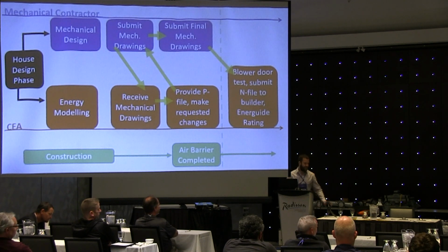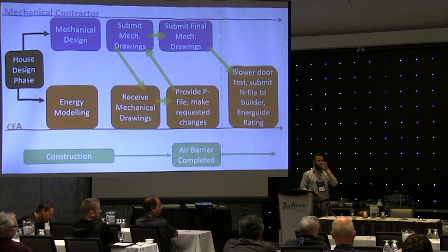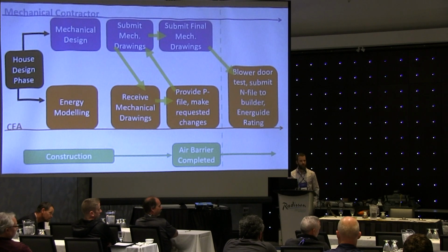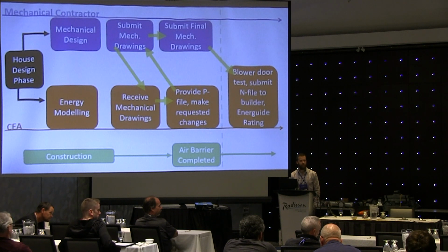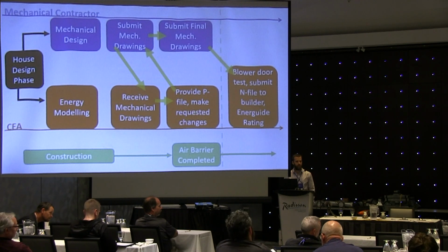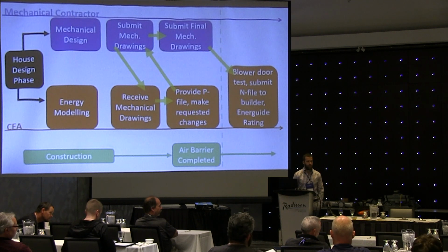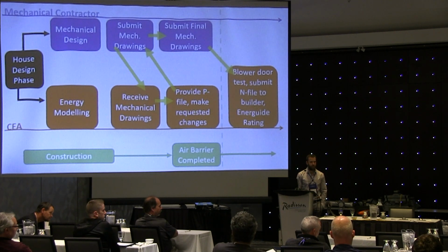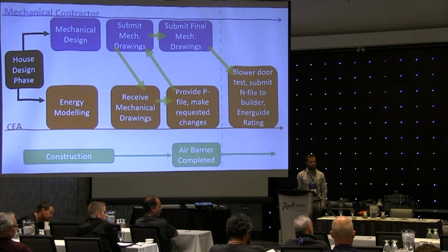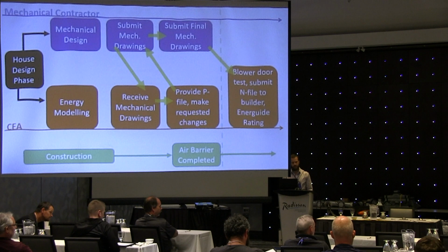The point that I would like to make in this next session is that in all these sessions where we're getting into better and better heat losses, which personally I totally support, the problem is that we're making an implied assumption which may be completely incorrect, and that is the 19,000 that Chris comes up with. We don't have any question about the validity of that if the house is built to plan. But we're making an assumption that that 19,000 is perfectly proportioned to the rooms in need according to the respective losses. In the case of an air distribution system, that is a wild assumption. That isn't the case in most design-installed systems today.